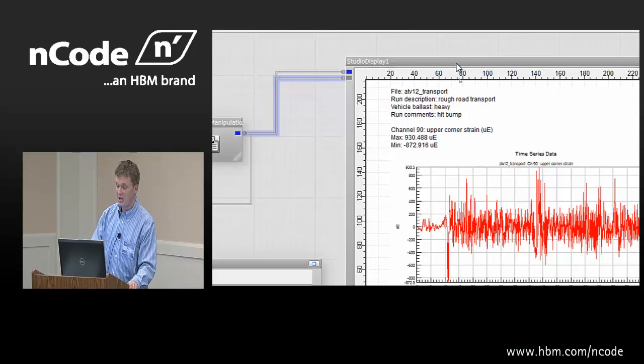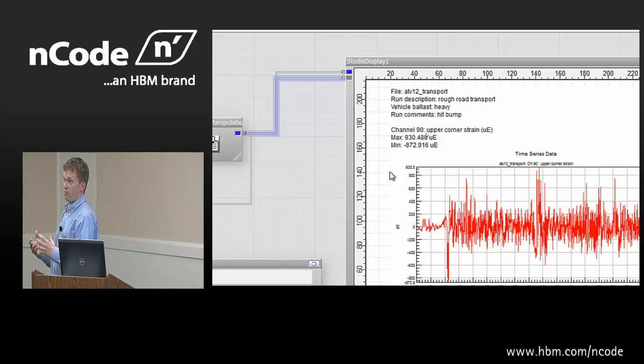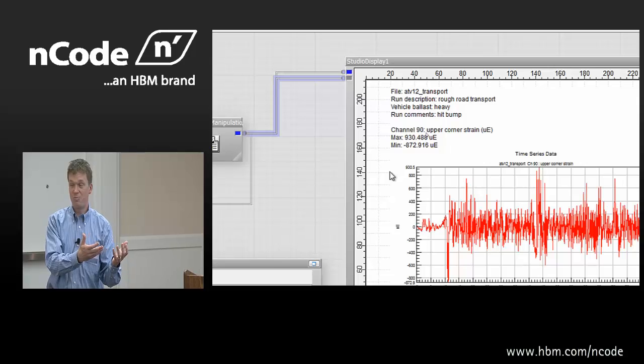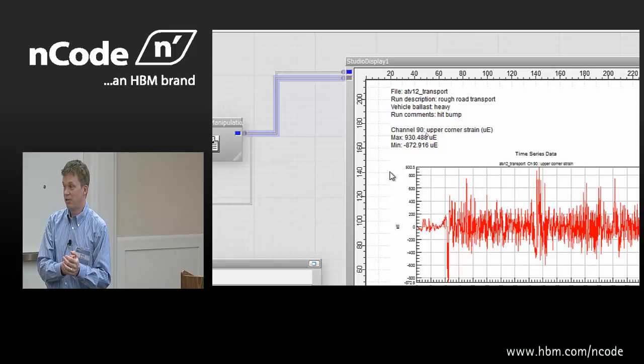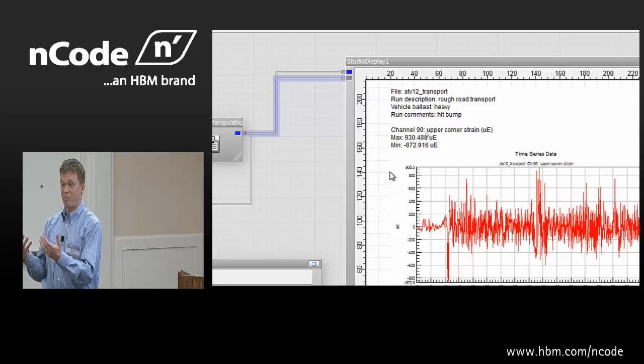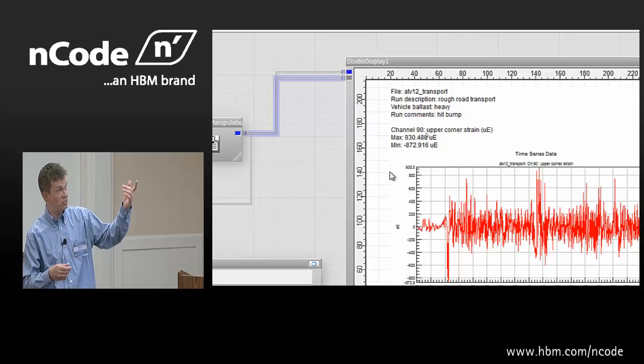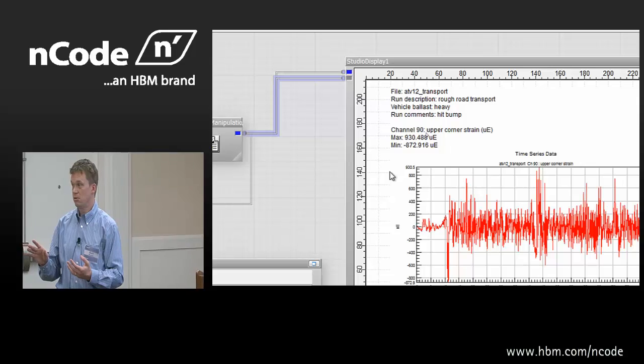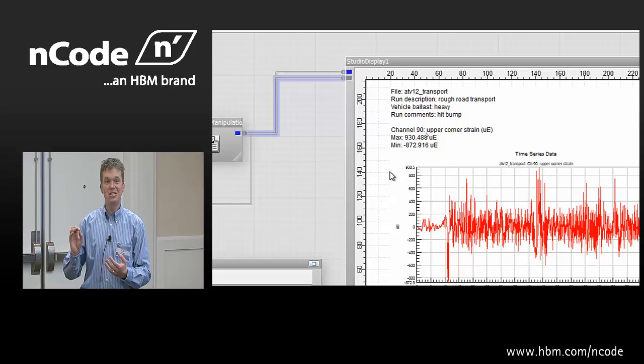So this could be just for reporting sake like this, just so the header of my report has the appropriate information filled in. It could be for fatigue calculations. It could be repeats information. Take damage per run and multiply by the number of repeats, and the number of repeats changes on whether I'm doing this transport run or a backfilling run or so on. Is this making sense here? How many people have used this, what we call test lookup, for metadata inside GlyphWorks? Okay. All right, good.